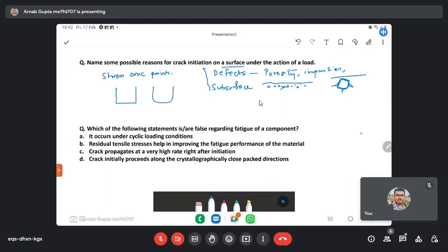They are made with a finite radius. This is done to prevent the stress concentration at these corner points. Otherwise, over time, there's high chances that the crack initiates and under the loading conditions, it propagates to these corner points.